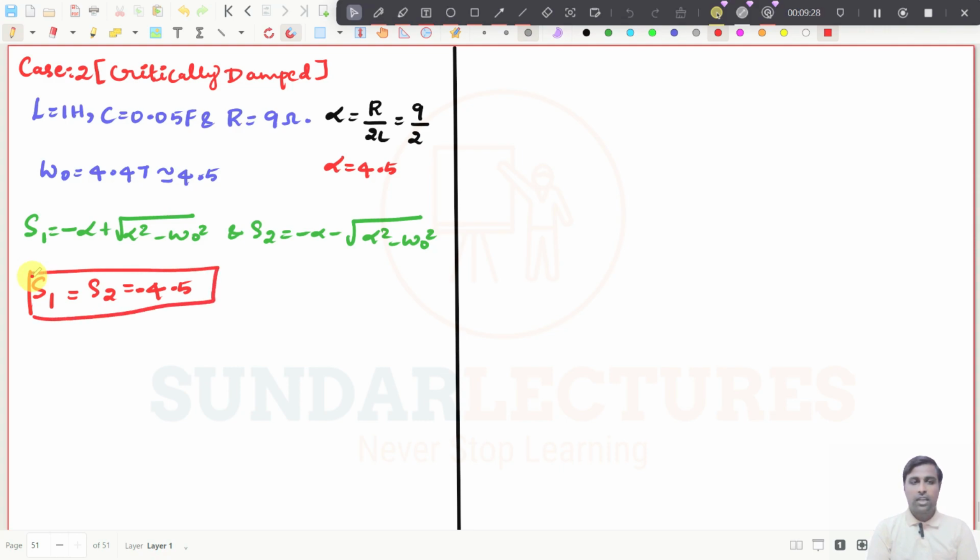And you see, if both the roots of the characteristic equation are equal, then what is the solution for the differential equation? The solution will be V of t equal to (a plus b t) into e power s t, plus 10 volt.